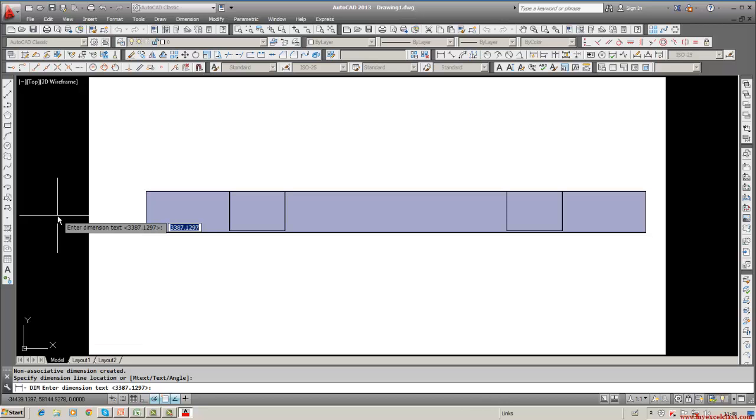Then the drawing you have displayed is about 3 times larger than the original drawing. Instead of 1000, it shows as 3,800. So the ratio, 3,800 divided by 1000, is about 3.8. That means the size is increased by 3.8, so all the lengths are increased by 3.8. Suppose we measure this length.